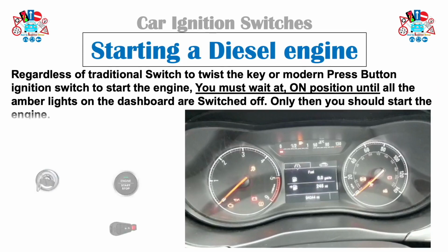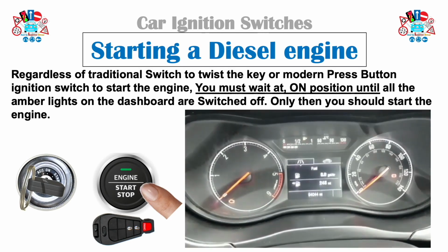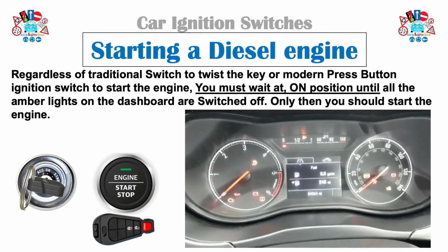Starting a diesel engine. Regardless of traditional switch to twist the key or modern press button ignition switch to start the engine, you must wait on the on position until all the amber lights on the dashboard are switched off. Only then you should start the engine.